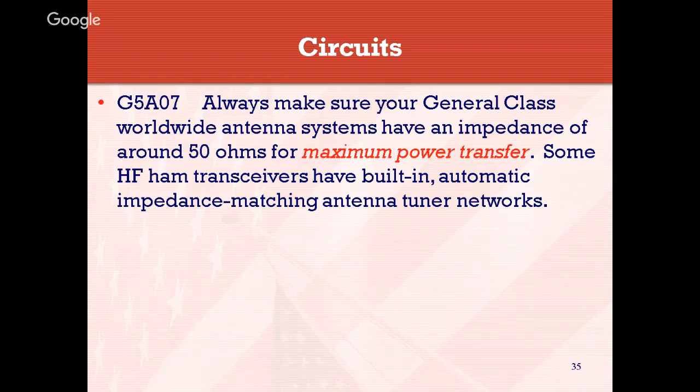What happens is you push a couple little buttons and you key the transmitter, and you hear this little whirring inside the radio, and you watch the little needle on the meter on the front of the radio. When it finds the resonant frequency internally to match that antenna, it's going to give you maximum transfer of power out from the radio through that tuner section. It doesn't necessarily mean the antenna is going to be efficient, but you're still going to transmit something out there.